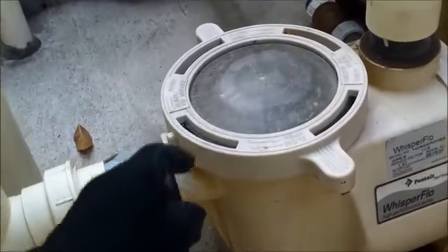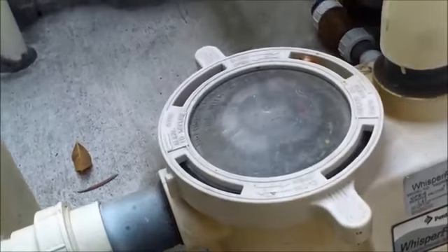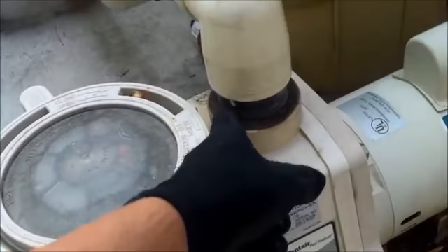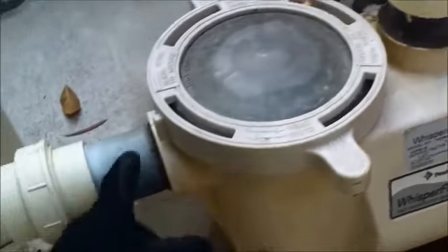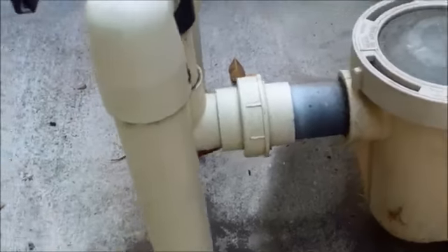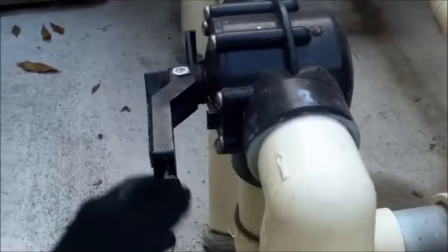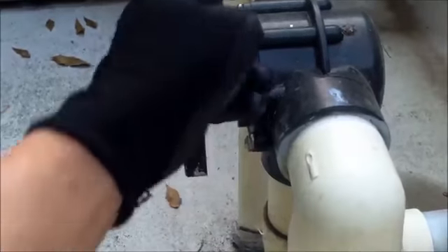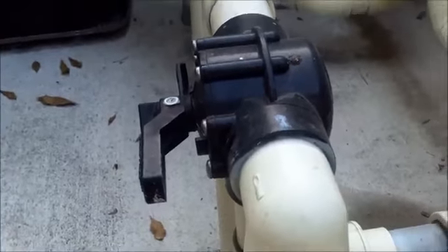So if your pool has a suction leak, it could be the O-ring. That's the main source of the suction leak usually. A leak at the discharge right here coming out of the pump. A leak at the intake of the pump. A leak at a union before the pump. And also the Jandy valve has an O-ring in the faceplate that could also be leaking.